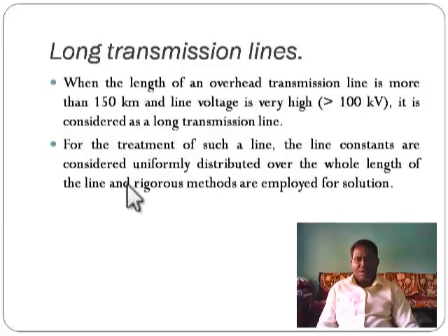We are not solving in an easier manner or in a phasor manner, as with the short line or medium line. We have to perform rigorous methods, with differential equations, to solve this kind of long line transmission network. We will discuss this in the derivation portion. Remember, the operating voltage for the long transmission line is more than 100 kV and the distance is more than 150 km. Let me move on to the next slide.